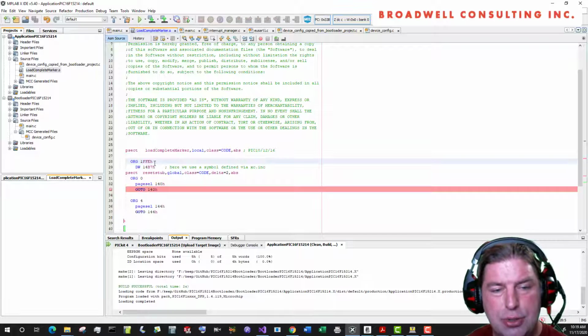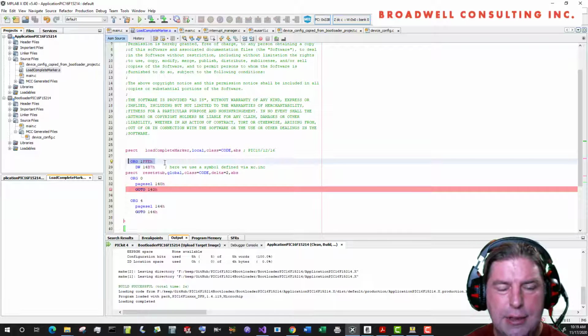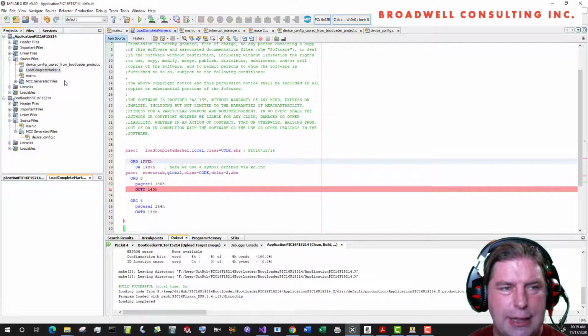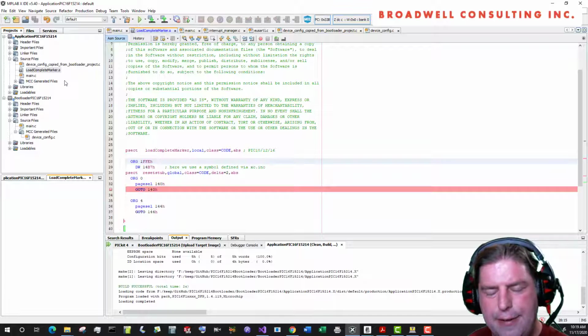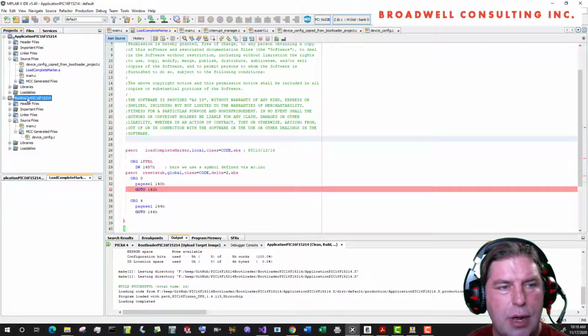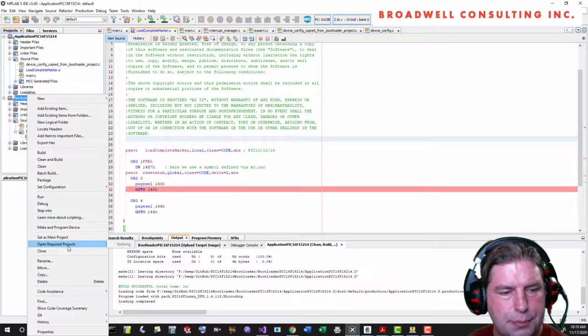If I don't do this, you may get an error that says you have conflicting values. That's because you tried to put something in here explicitly, and the linker, based on the ranges it had, also tried to put some data in there. And so you have a conflict. To avoid that, you add that -FFF, -FFF to the ROM memory ranges. So let's go ahead and run our bootloader now.